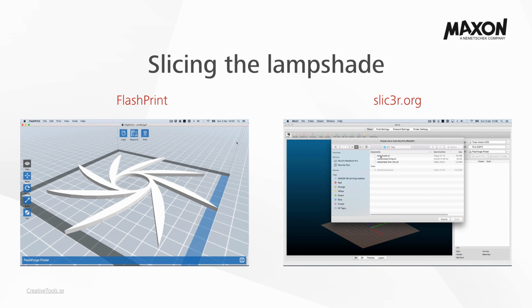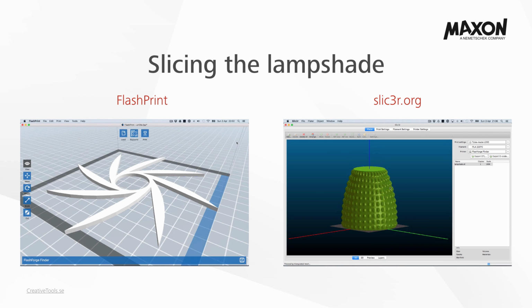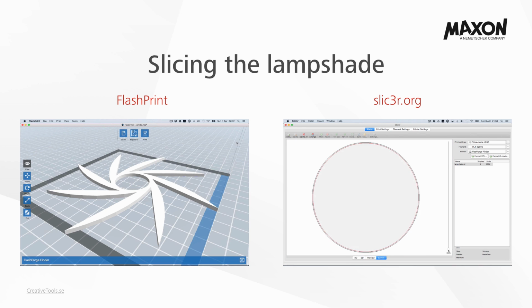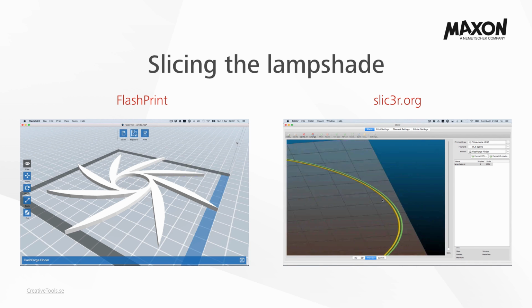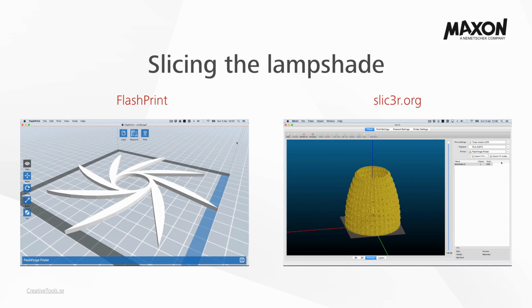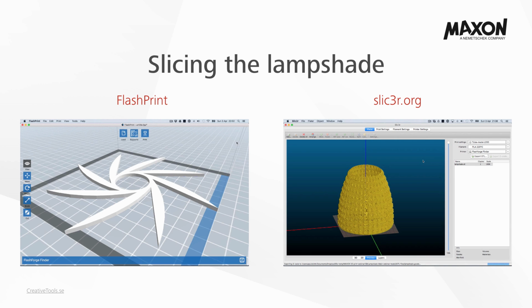Since the FlashForge Finder follows an open standard for 3D printing, the machine can be used with third-party slicing software. To demonstrate this, I imported the lampshade into an open source software called Slic3r, where I created a profile based on something called vase mode. This will affect the printing of the shade in such a way that only the outer contour is printed, and it does so in the shape of a continuous spiral. This creates a thin-walled, seamless surface, which is perfect for making a lampshade.